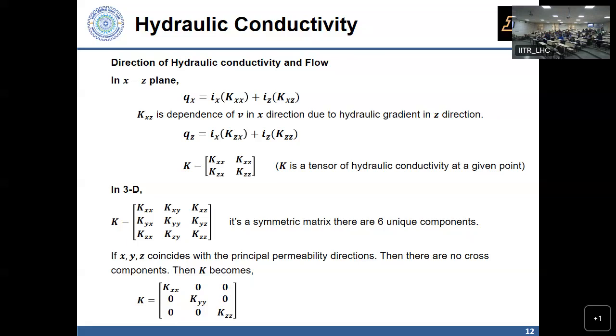Okay. So for 2D horizontal flow, we talk about the idea of a transmissivity. Same idea: capital Q x prime is the flow throughout the thickness of the aquifer in the x direction. Capital Q y prime is the flow throughout the thickness of the aquifer in the y direction. So we are not worried about flow components in the z direction.